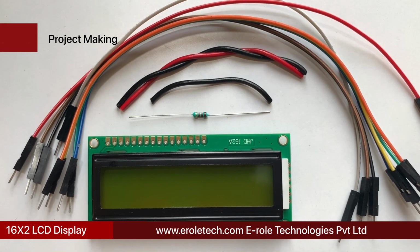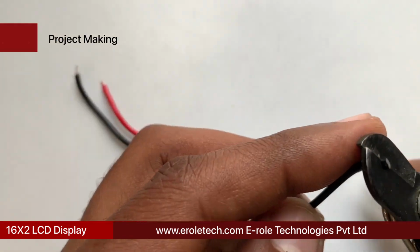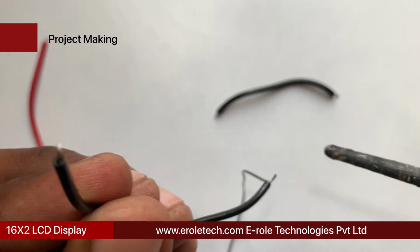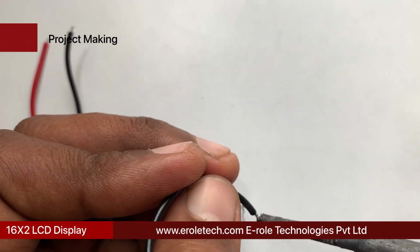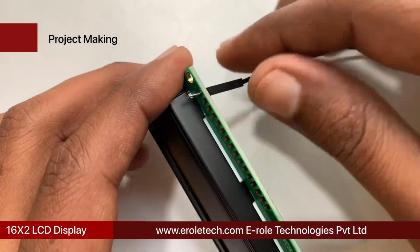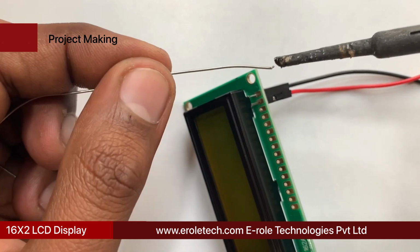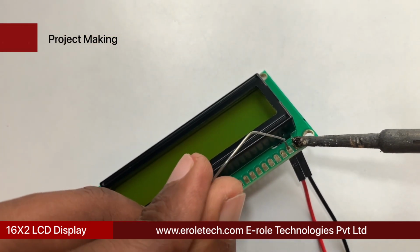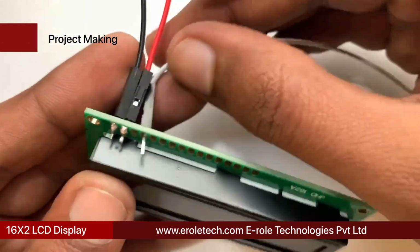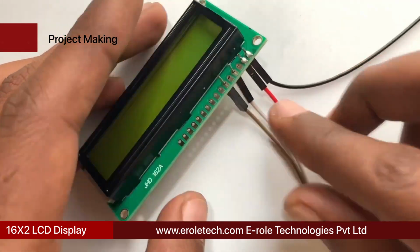Now we will assemble our hardware. We will take 3 wires, 1 red and 2 black. We will use these wires later. Now we will solder a black wire at hole number 1 and red wire at hole number 2 of LCD display. Now we will solder a white wire at hole number 4 and brown wire at hole number 6 of LCD display.